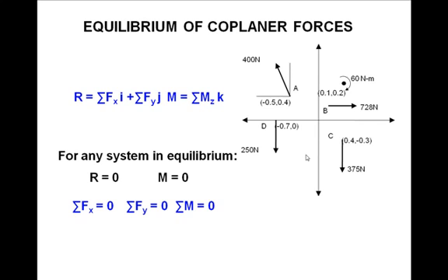So these three, sigma Fx equal to 0, sigma Fy equal to 0, sigma M equal to 0, form the equilibrium equations for a coplanar non-concurrent force system.